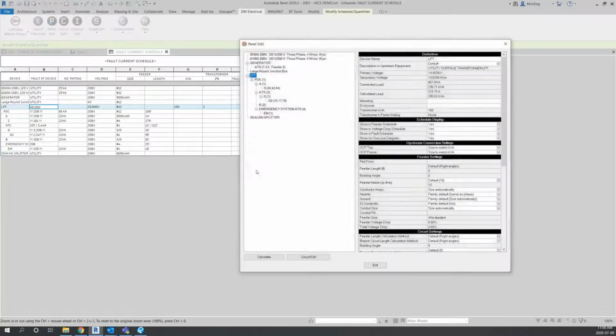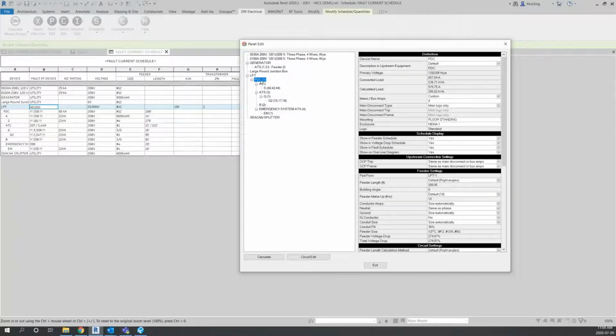But basically, you come into Design Master. If you get your panel sizes set, we'll size your feeders, and then the fault calc and the voltage drop kind of fall out automatically based on that. Yeah, I think that main bus size on the PDC not being set properly is screwing everything up. Yeah, so the PDC doesn't have a bus size and whatnot.